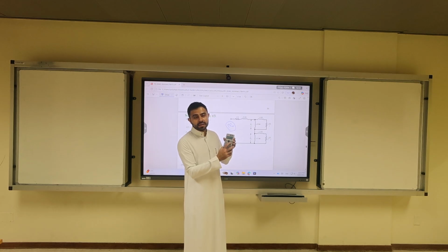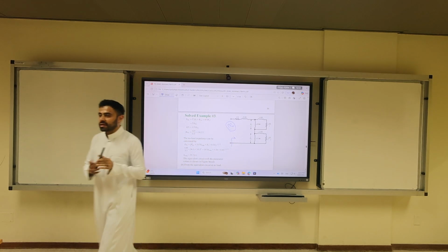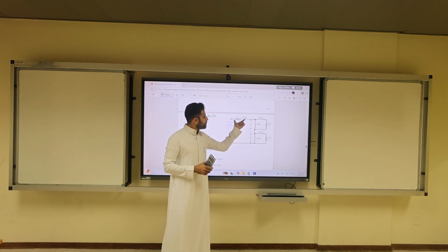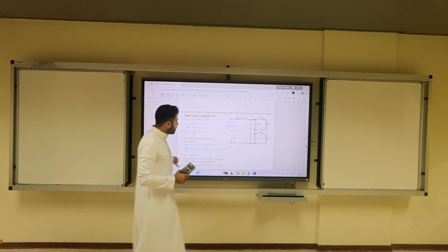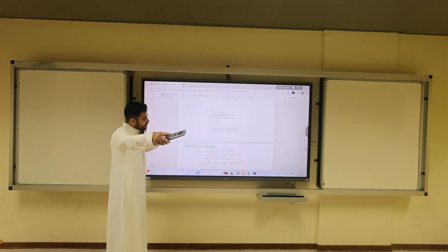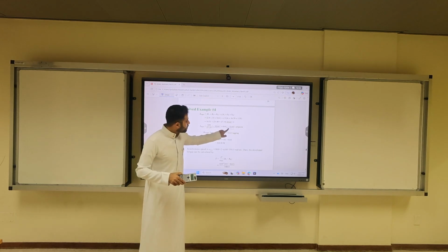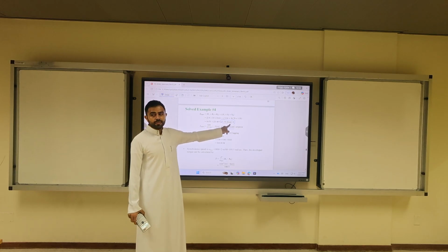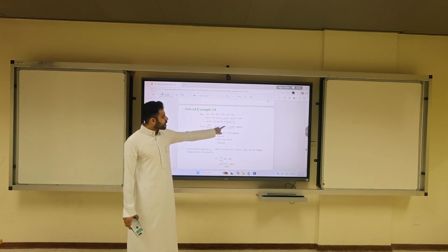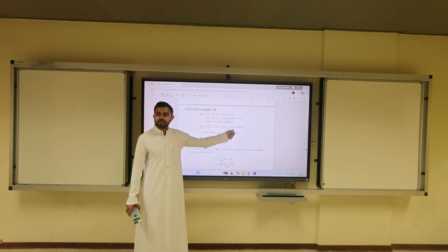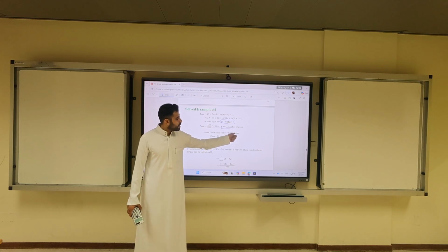Do not waste your time in the exam. The final exam might be a little bit lengthy. Time is important. Okay. Then you add these two with this R1 plus jX1. And then you should verify using calculator. Those who are in the career fair, please make sure you get this number accurately. And usually the angle of the impedance is the angle of the power factor, but let's wait until you get the current. So current is lagging the voltage because it's minus, so that's why it is 0.61 lagging.